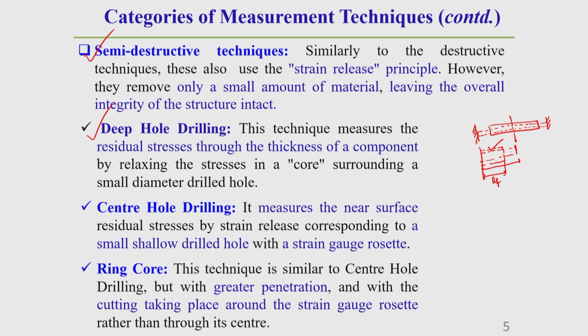So, depending upon the locked-in stress, that can be tensile or compressive. Depending upon this tensile and compressive strain, the residual stress can also be tensile or compressive in nature. This you should keep in mind. There are different types of semi-destructive residual stress measurement techniques, like one is called the deep hole drilling technique, another is called the center hole drilling technique, and another is called the ring core technique.